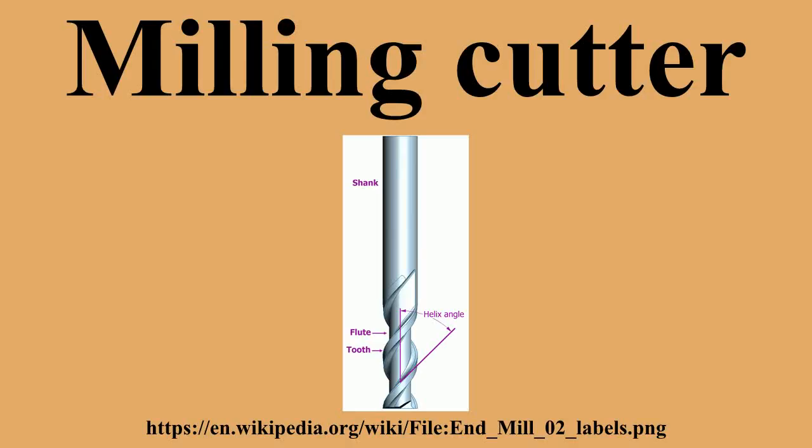Often, for jobs of a large number of parts and days of machining time, the cost of the tool is lowest of the three costs. Material. High-speed steel cutters are the least expensive and shortest-lived cutters. Cobalt-bearing high-speed steels generally can be run 10% faster than regular high-speed steel. Cemented carbide tools are more expensive than steel, but last longer and can be run much faster, so prove more economical in the long run.